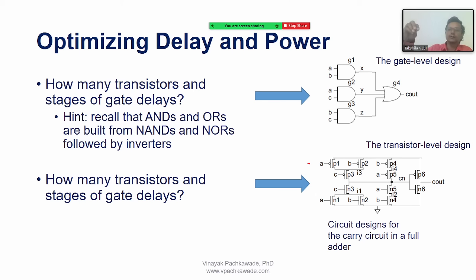Because after the logic synthesis tool, when the netlist is generated by the logic design team, the gates are synthesized. Whether you call it a gate level design or transistor level design, inside the gate there are transistors, so it's already automatically generated by the tool. That is then either dumped into the FPGA, or sent to the foundry, or sent to the physical team.